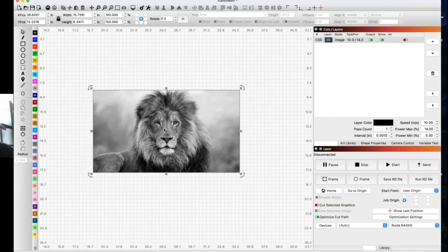You have to do a lot of matching of DPIs, and there's a lot of stuff to be concerned about before you even bring it in, if I'm not mistaken. I remember having to match DPIs and that being a concern. It would give you an error if it didn't match the laser's projected DPI output and that kind of stuff. Yeah, and if you go too high on it, it'll actually throw a crazy image out. Luckily, Lightburn does all the processing internally, so no matter what you bring in and no matter what you're going out to the laser, it's smart enough to make the image correct on the output side. So there's less to be concerned about and much easier, with a lot less thought put on the user end than with some of these other programs.